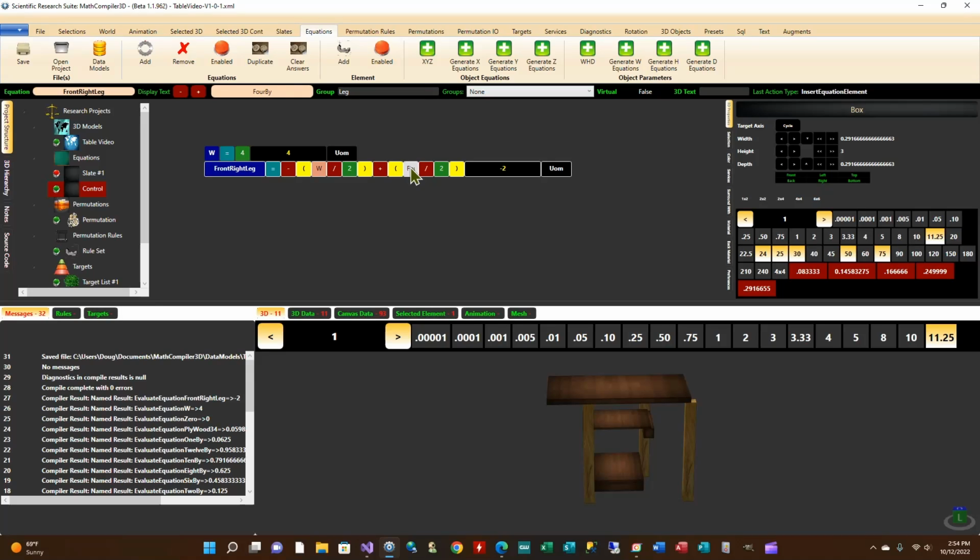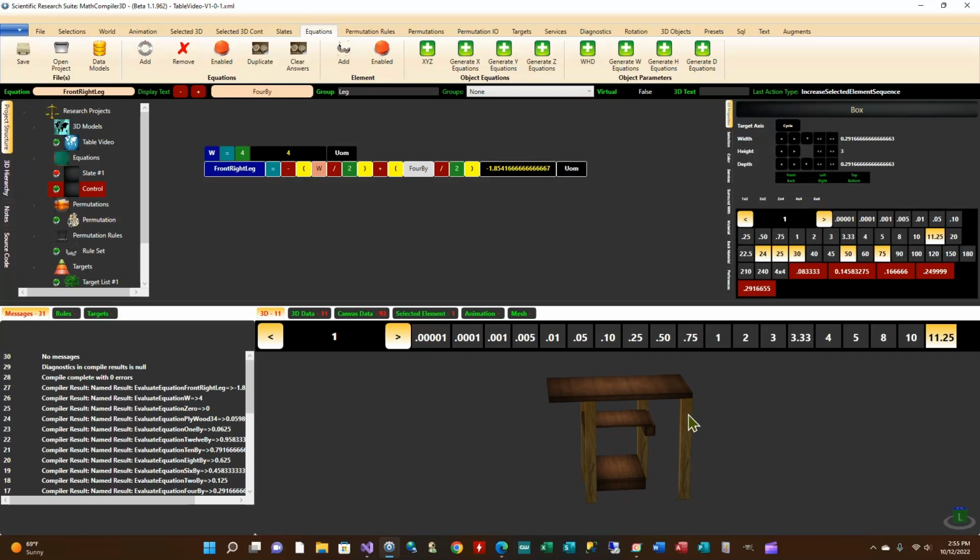If I had to put a lowercase f on this variable, then it would not calculate properly and give you an error. So now that 4 by is selected, I'm going to go Control plus and lengthen out so we can see the entire name of the variable. Now I'm going to hit F6, and notice how the leg is even with the edge and right where we want it to be.